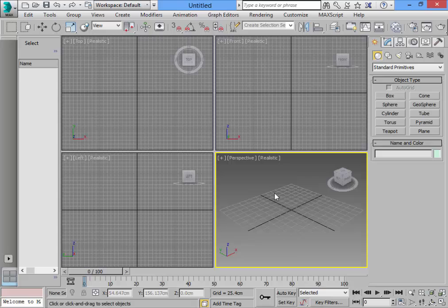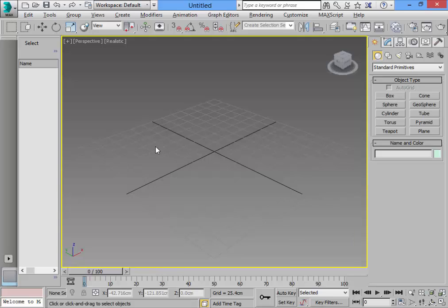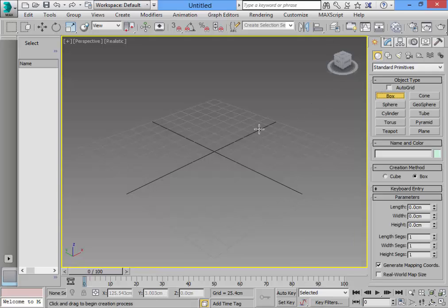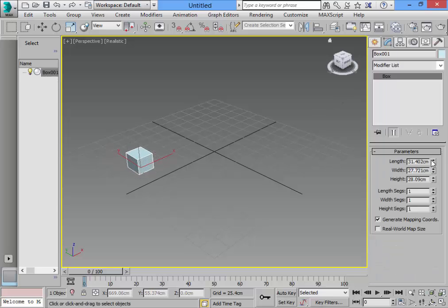And I'm going to save now, sorry, I'm just going to set up an environment for making that rigid body practice. From here, I'm just going to build a simple box. Okay, the box is going to be something like this. And from the modify section, I'm just going to make it exactly a cube. It is 30 centimeters in every dimension.